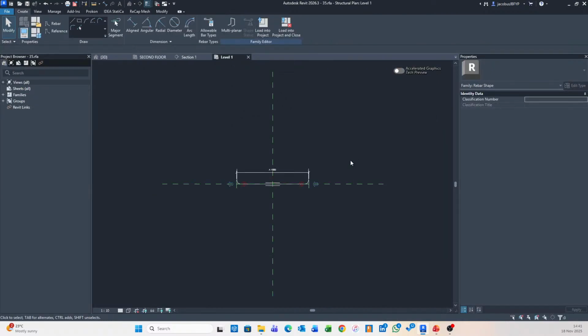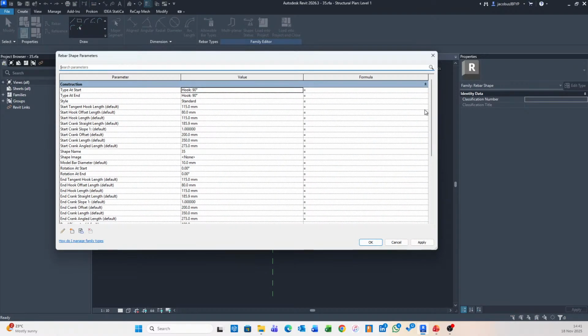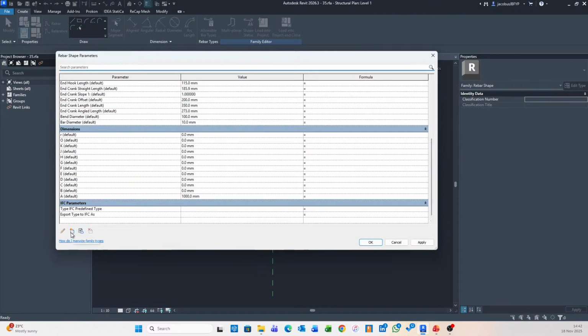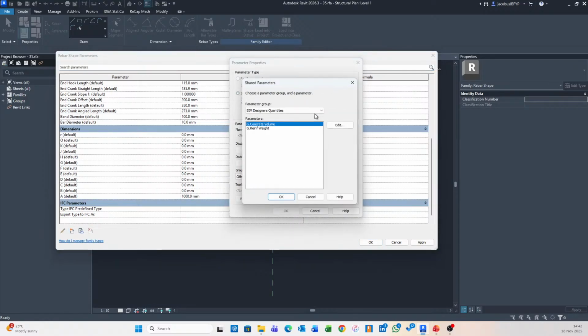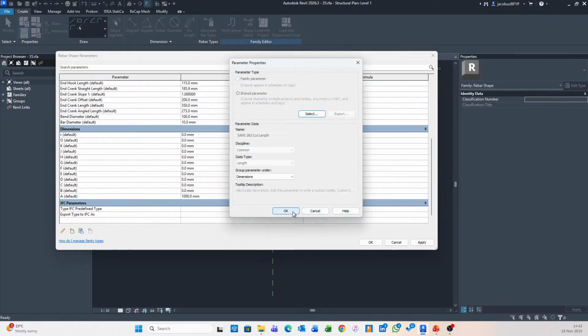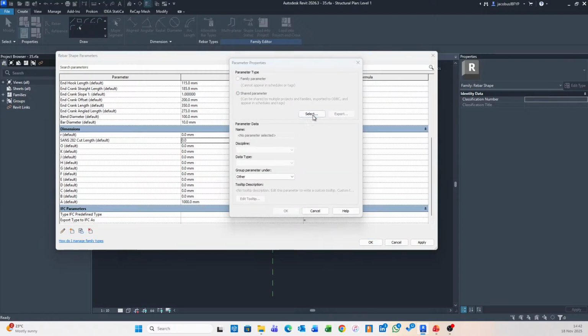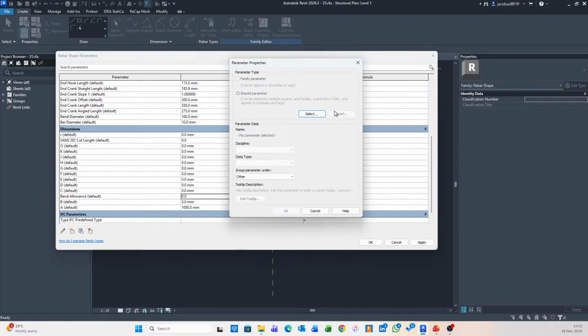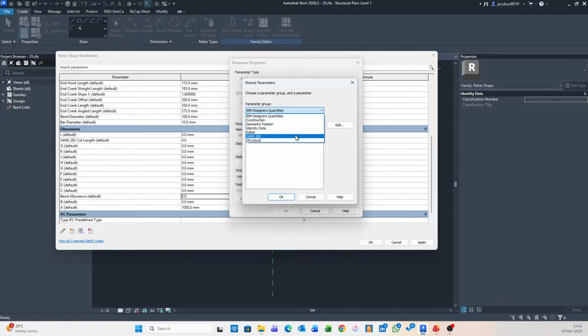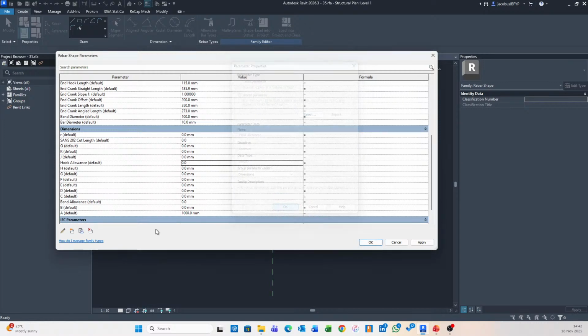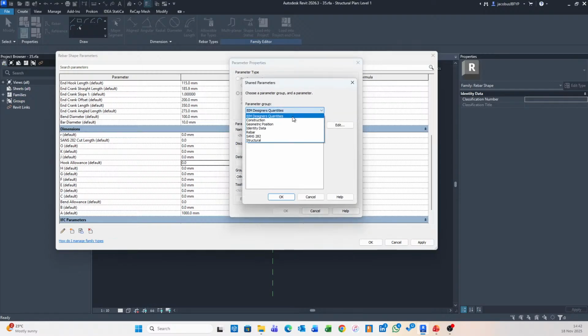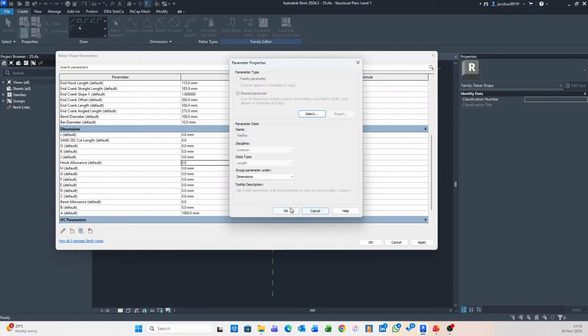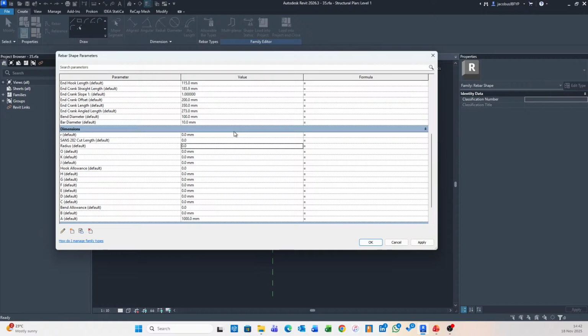And again, I created some shared parameters. So just keep in mind that you do need to create a set of shared parameters. I am going to say new parameter, go SANS 282. There's a SANS 282 cut length, and I'm going to add that parameter. I do need to add the other three as well. So there's bend allowance, because they can form a part of my formula. So there's hook allowance, and let's go for the last one, which is radius. Okay, these are as per SANS 282, the different tables for mild steel and high yield steel.